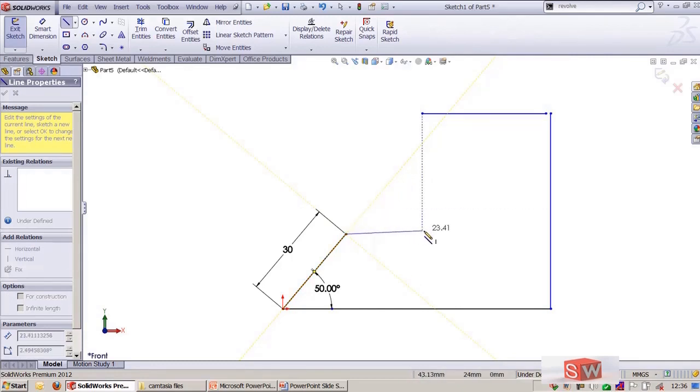And there is one more thing I want to highlight here. When you create a line segment, you can also create an arc continuing with that. Before that, let's complete this inferencing. You can see here when I move near to any of the line segment, it will show you the end point, or I can drag from here to get this midpoint. Now I will show an example. From here I will get a point, and from here also you can see a midpoint. You can choose from here. So this is what we call inferencing point.